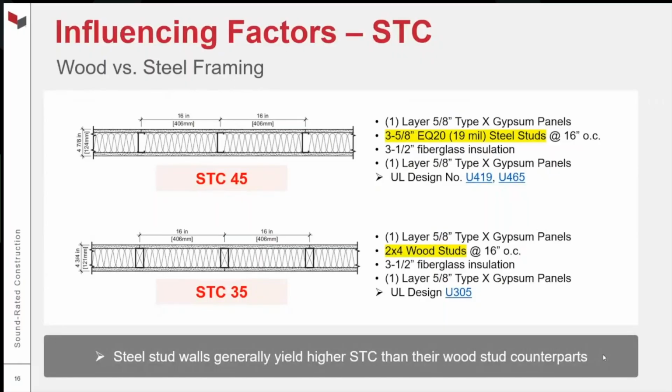That's going to change, and I'm going to blow that up in the next couple of slides, because once you start getting into very stiff steel studs, like 16 gauge, 16 inches on center, they start to behave a lot more like that 2x4 wall that you see on the bottom. So we'll see that coming up.